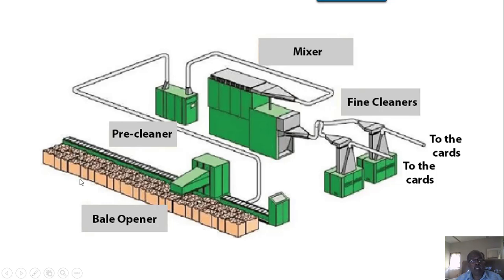So this traversing and lowering of the chassis to pluck the cotton, and when this kind of bale opener in Rieter line, you have some difference, and in Trützschler line you have some difference, that one roller is provided in one instance and two rollers are provided in another instance. So that again is a philosophical difference.